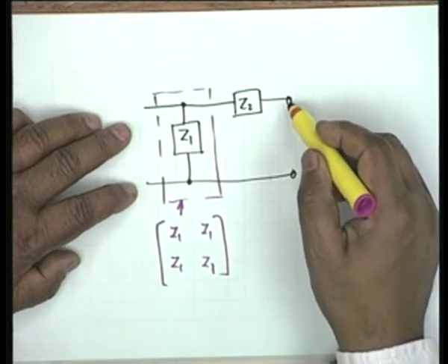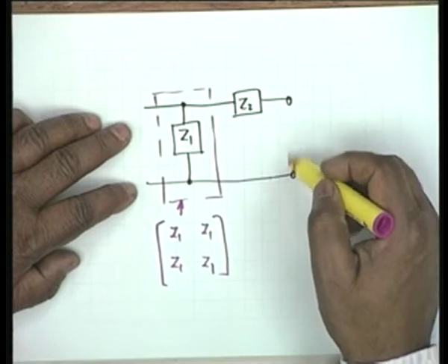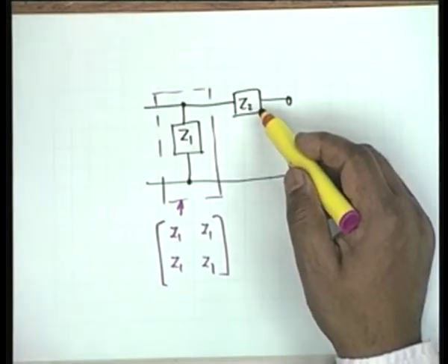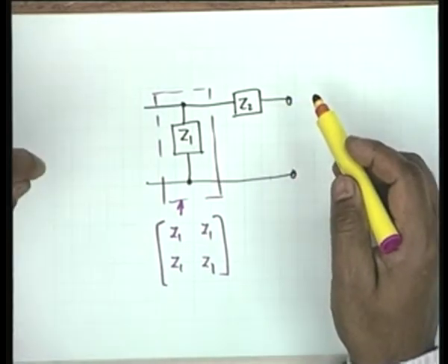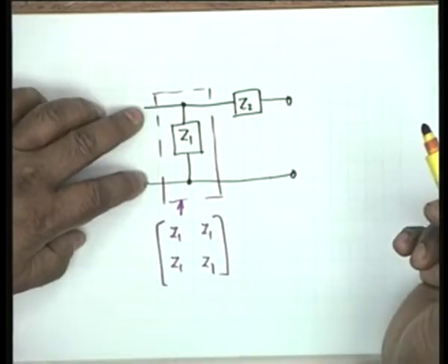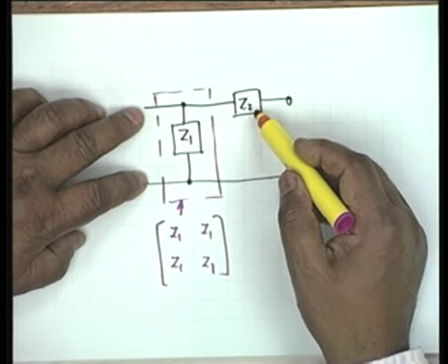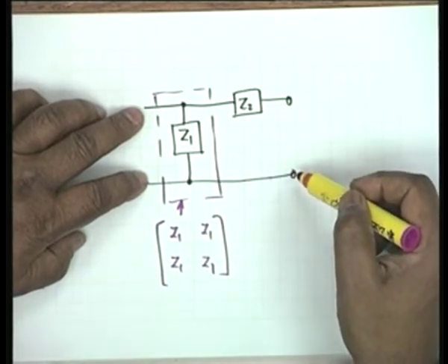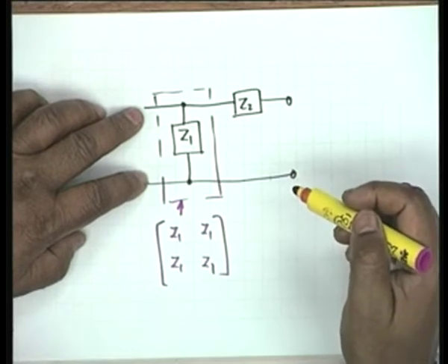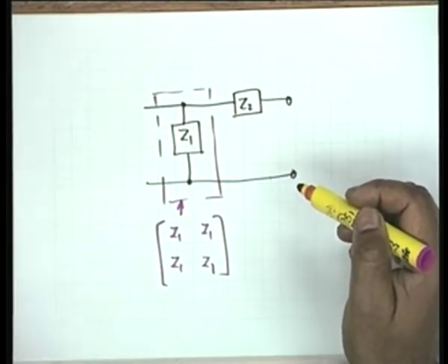If I find Z12, I have to connect a current generator here, an impedance in series with current generator has no effect. Alright. It does not affect Z21, I connect a current generator here, what is here it does not matter because I have kept this open. Alright. It affects Z22, that is the only parameter it affects. How does it affect?